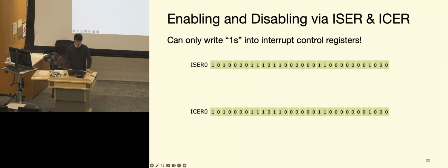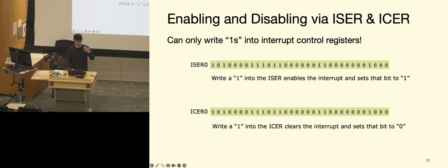Okay, as we mentioned in the last lecture, a few slides before, we have 2 of those registers, the enable and the clear enable registers, each controlling the interrupts, and they essentially do a 1-bit mapping to each of the interrupts.